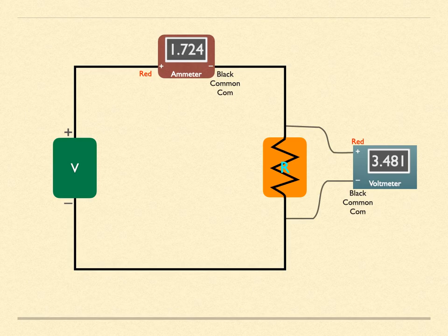If the voltage source does not have its output labeled, using a voltmeter in this manner can determine it. If the measured voltage is positive, then the red terminal is connected to the positive or high potential energy side of the voltage source. Now, this is using the convention that current flow is of positively charged particles. But in electrochemistry, we have to worry about where the electrons are because the chemistry involved depends upon them. In the next lesson, we will look at electric circuits and electrochemical processes.